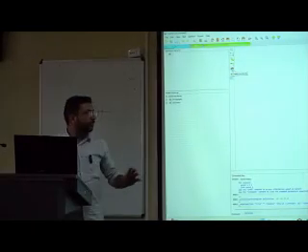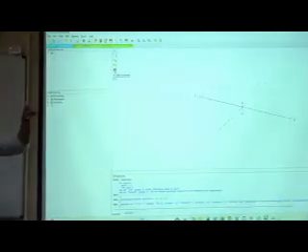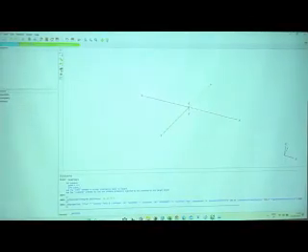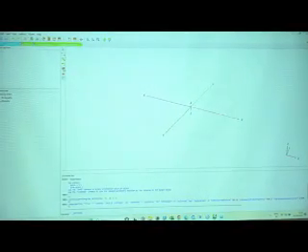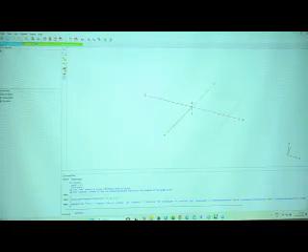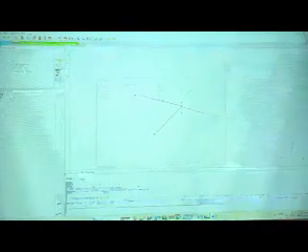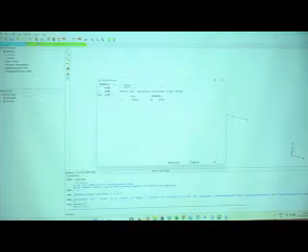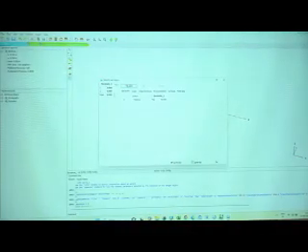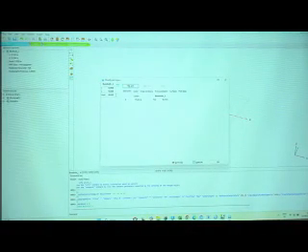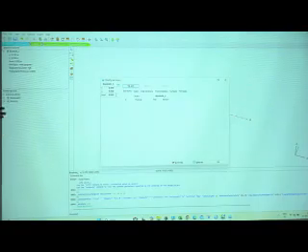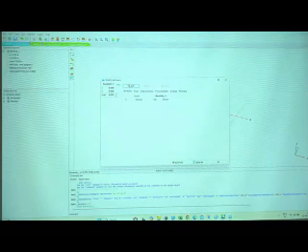So after this we have this rectangular, square part of the soil domain, that is 15 meter into 15 meter. Now in 3 dimensions we need the third dimension. Here you have the water. If water is at 20 meter below the ground surface, you will write -20. If it is at the surface, it will remain 0. So you can change the depth of the water accordingly.